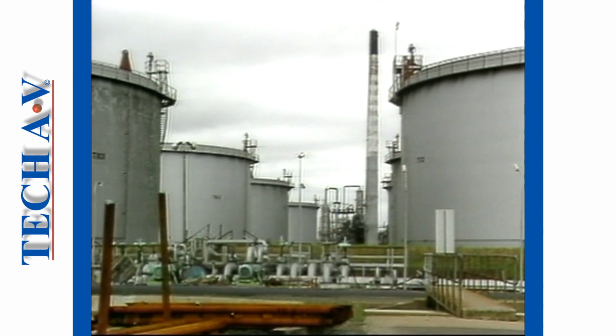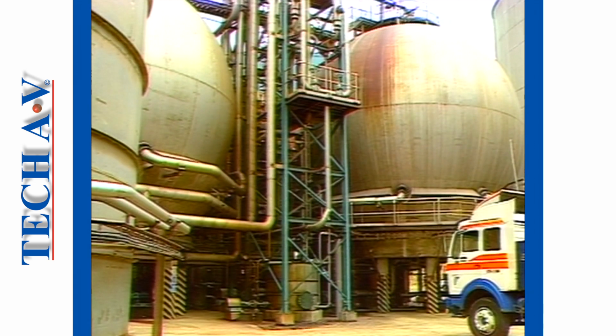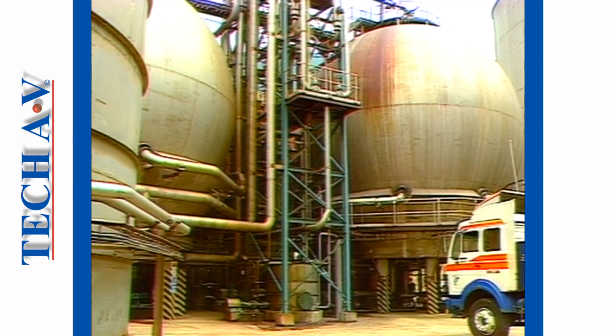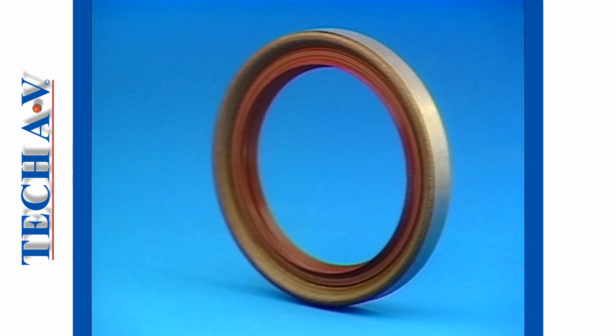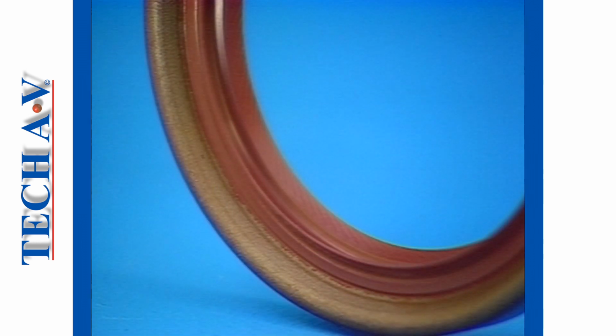Some applications, especially in the chemical industry, require materials that can withstand very corrosive conditions and temperatures between -20 to 200 degrees Celsius continuous operating. Specially developed fluorocarbon materials are produced by leading seal manufacturers, but the cost of the seals can be as much as 30 times more than nitrile. A popular trade name for such a material is Viton by DuPont.